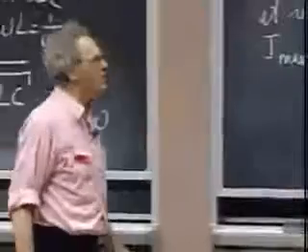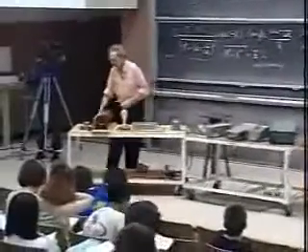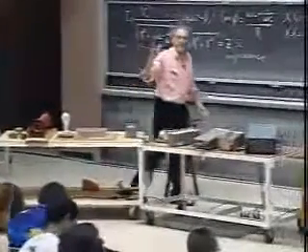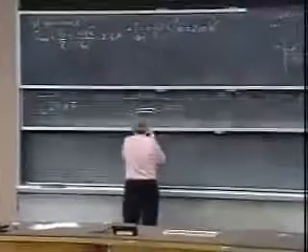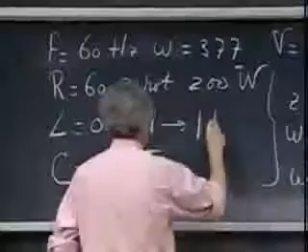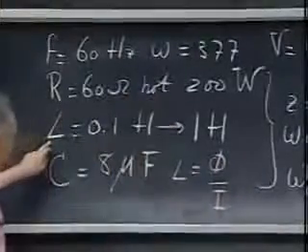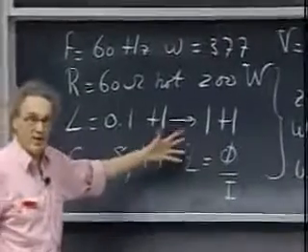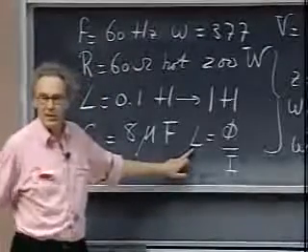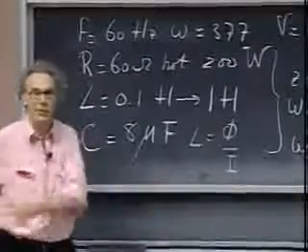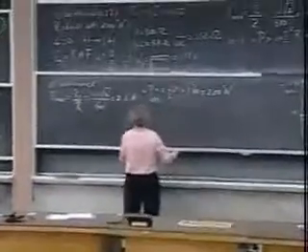And I want to catch two birds with one stone during this demonstration. I'm going to teach you a way that you can increase L, something that we have never discussed before. I have here ferromagnetic material, which has a value for kappa somewhere around 10, 12. Let's say it is 10 for now. So that means that if I bring that iron core inside, I could make this go up to 1 Henry. Because remember, the meaning of self-inductance is the flux divided by the current in the solenoid. And so if you bring in ferromagnetic material with a kappa M of 10, then the flux goes up by a factor of 10. The current remains the same, and therefore your self-inductance goes up by a factor of 10. So you see that you can make a variable self-inductance by bringing in ferromagnetic material and by removing it again. And so the question now is, how high should L be to get on resonance?